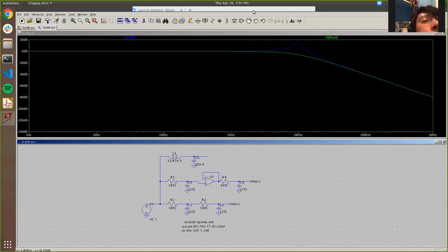Why don't we just always use an inductor capacitor filter rather than a resistor capacitor filter? That's a great question. Price-wise, inductors can be more expensive, and they're also a lot larger. The inductor is a coil of copper, right? Wrapped around something. It could be air or iron or some type of core. And that just physically takes up more space than a resistor does. So that could be one reason why you would rather use a resistor.